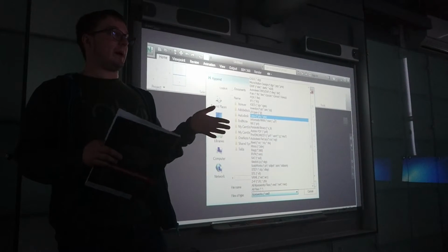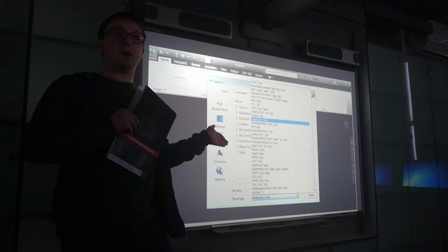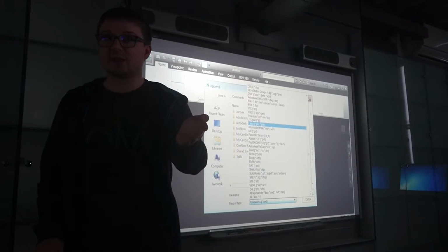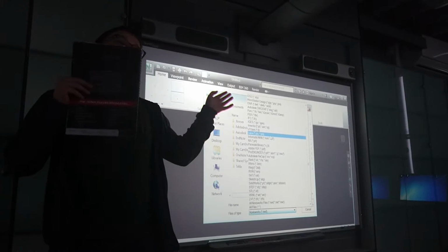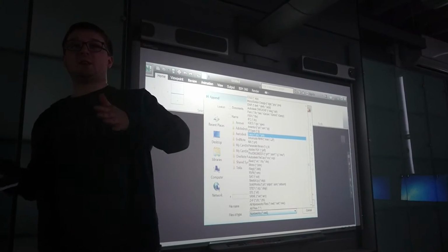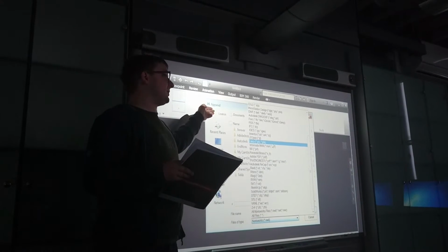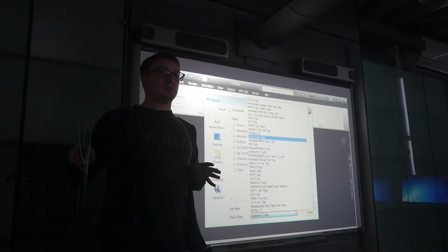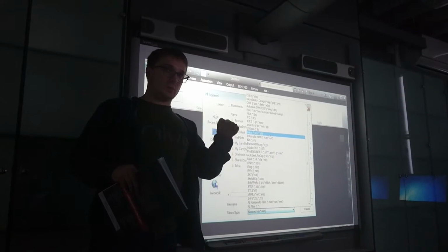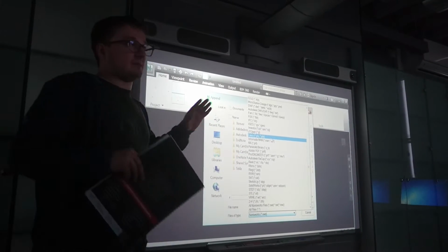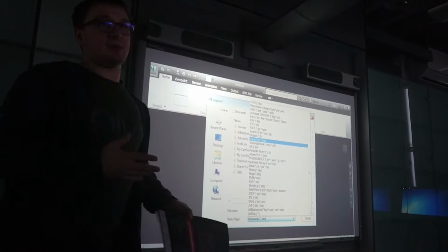Like when you open IFC from different software, there is geometry missing. Why? Because, like Martin also said, there's certification in exporting. Every single one of these programs is certified that we can export IFC files, but nobody is giving an IFC certificate in importing. So basically, what I would advise you, if you're working with Revit or Autodesk products, try to export them as native files. So RVT, whatever it is, DWG, not IFC. Just for the future. So generally why I like it, because you can simply open every file.